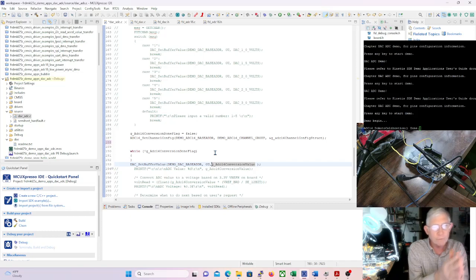And then the A to D converter's results will internally be written to the DAC, and then the DAC is going to output what the A to D converter is converting. And we're going to display one channel as the actual signal coming from the signal generator, and the other channel as the output from the DAC, which should more or less match it. And then we're going to increase the frequency and watch and see what happens.